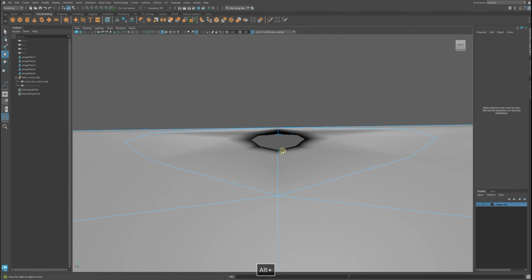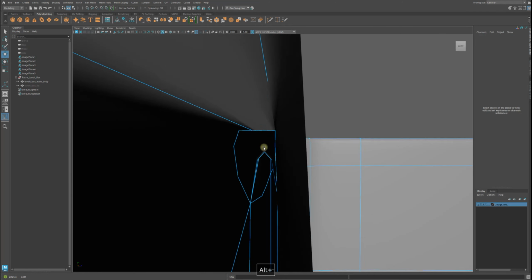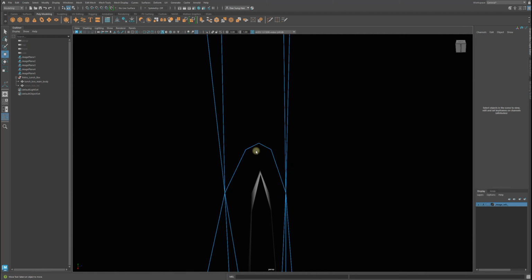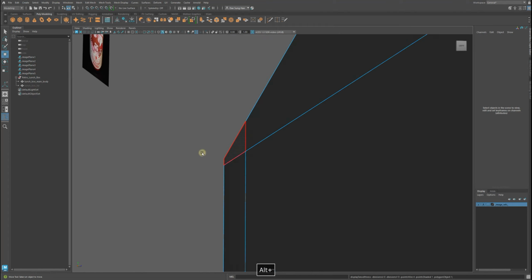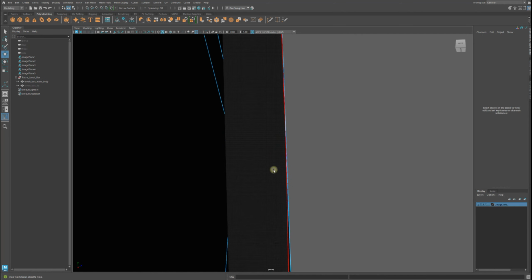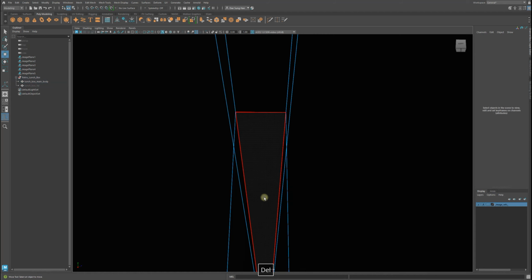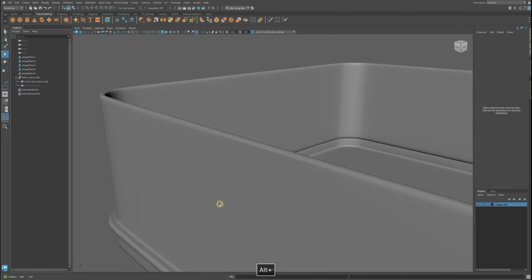It does that. So when you press smooth and then there's a face inside, it wants to squeeze on it and damage it. So press 1. Select that face, hit delete. I deleted it, but it's still there. Select it again because it's two faces within one. Now it's gone. Now if you press 3, it's fine.